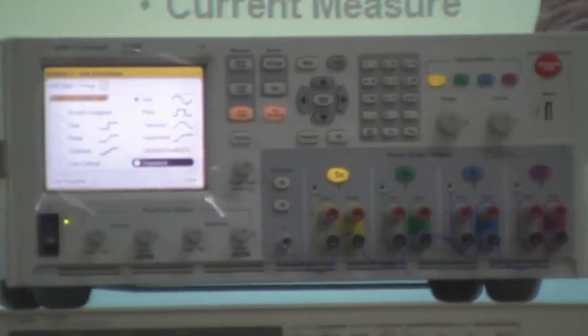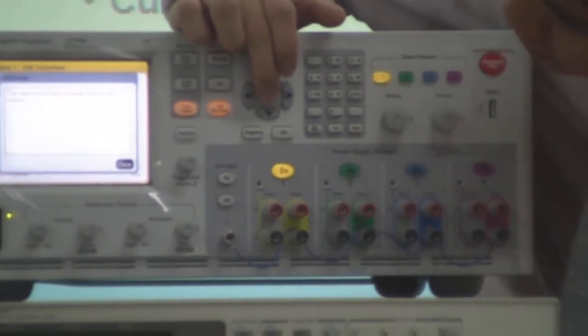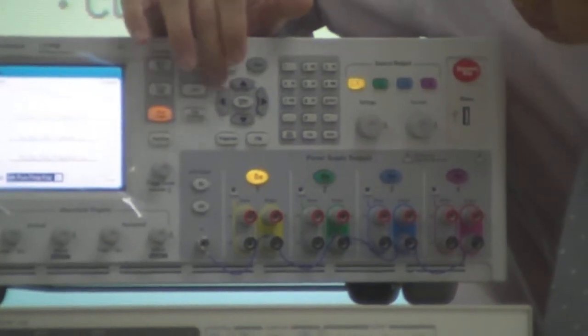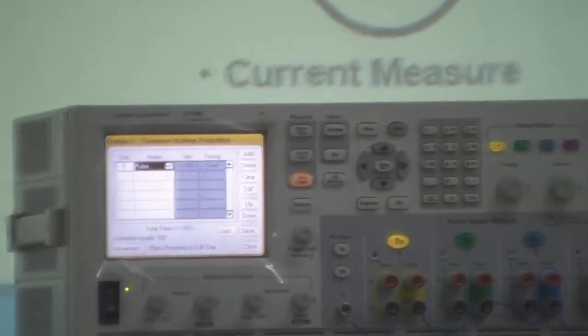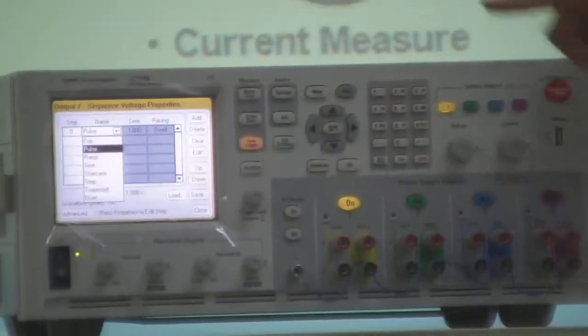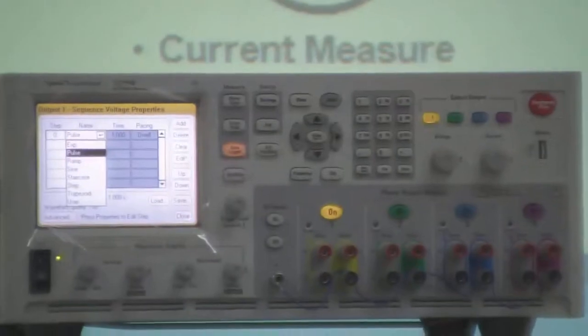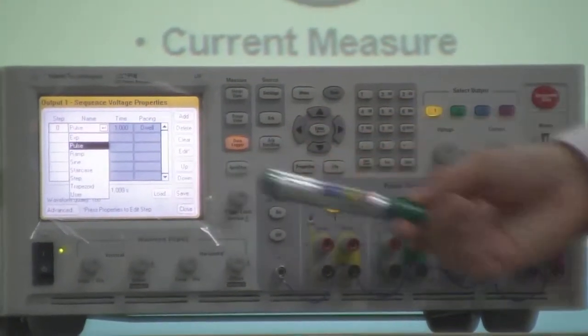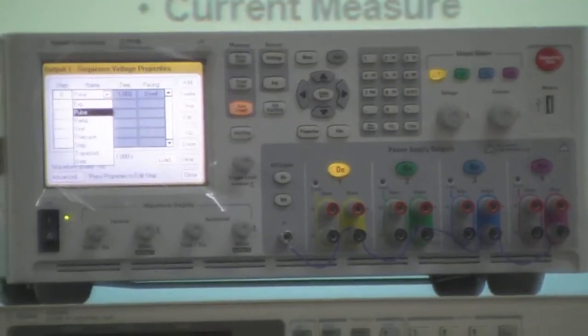So if you look here, you're going to see a sequence function. You click on it. Let me stop the R first. R properties, sequence. You're going to see this list right here. In each one of the slots on the list, you can select the different waveforms. If I open the drop-down menu, I can select sine wave, trapezoid, ramp, and you can configure this list to whatever you like. You can have 4 or 5 different waveforms cascaded with each other, and it will come out at the output exactly the way you programmed it.